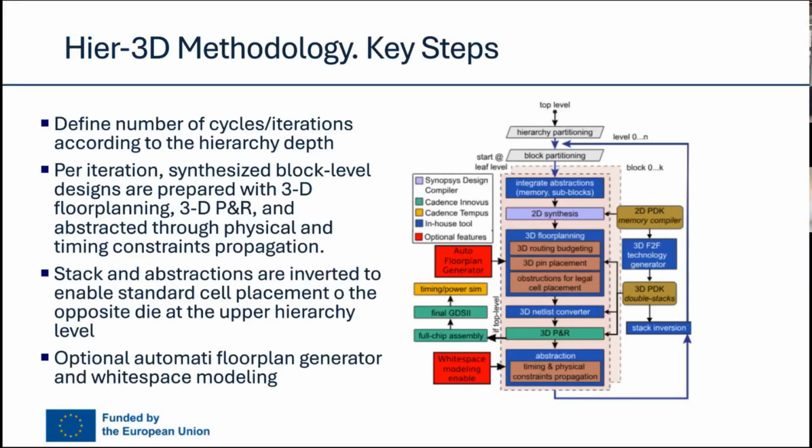On this slide, you have the complete flow that we have in hierarchical 3D. You just see that we start with hierarchical partitioning, then we can start with implementation of every block, then we do the 2D synthesis using the standard PDK with the additional definition of methodologies and the IPs with extension. Then we can do the 3D floor planning with budgeting, placement, and legalization.